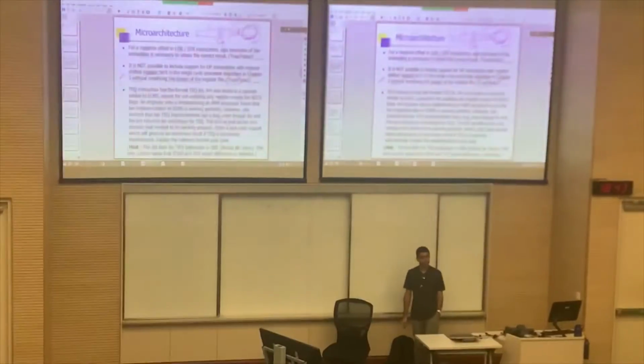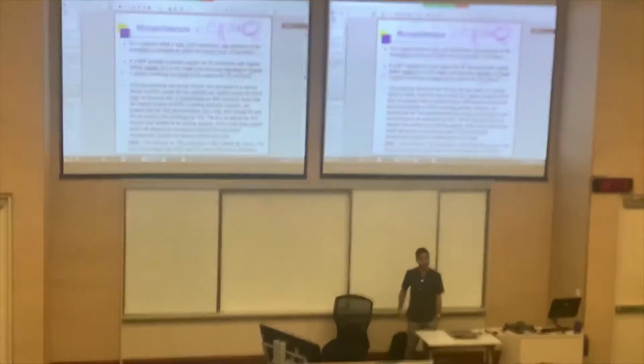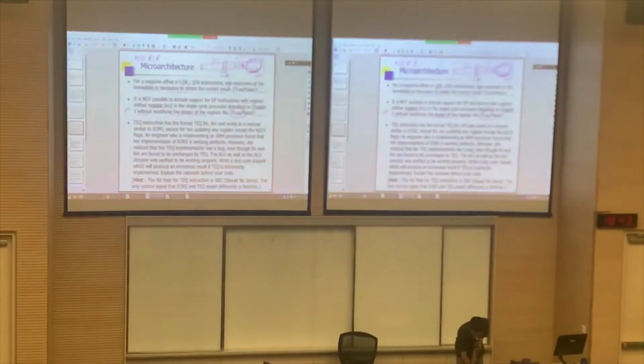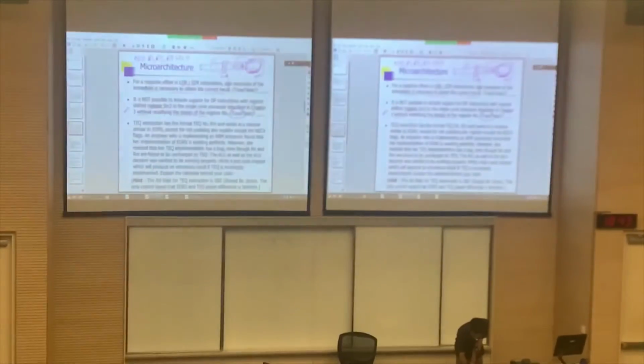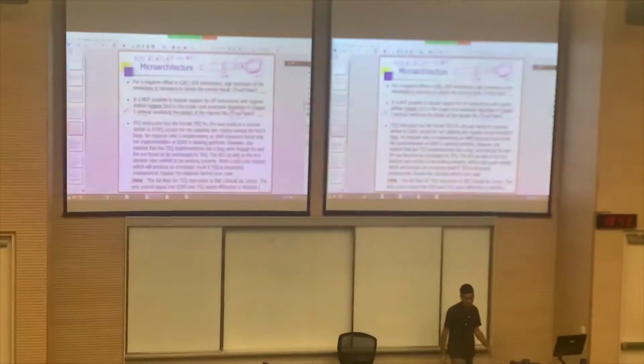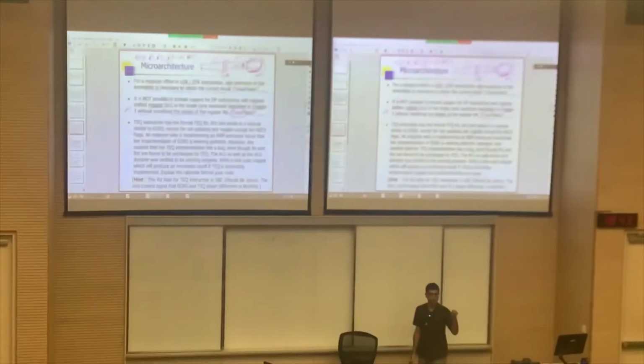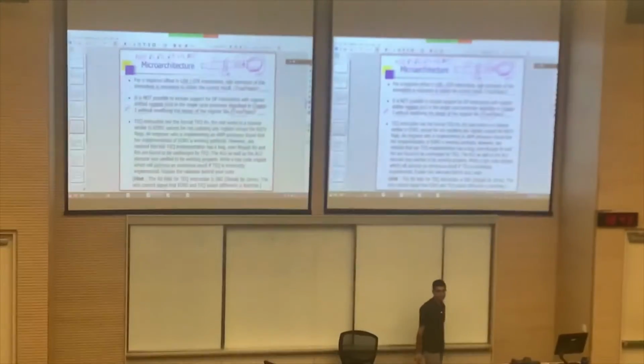For register shifted register, how many registers do you have to read? For example, if the instruction is something like, say, add R1, R2, R3, LSL R5. So here your second operand is R3 shifted left by an amount specified in R5.